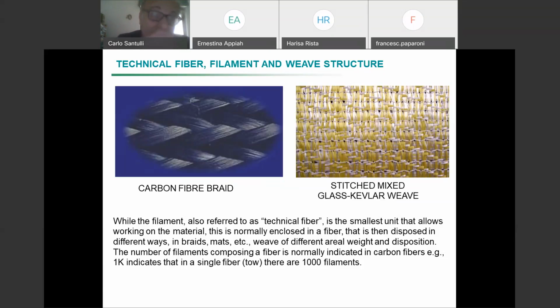It's simpler, especially working with waste. If you have some old glass fibers which you want to recycle, you try to remove the resin as much as you can, and then you chop everything and you put it into a new material in random orientation because you don't control anything really. But of course, the performance is much lower, and you cannot guarantee, for example, a tensile strength in one direction or two directions.